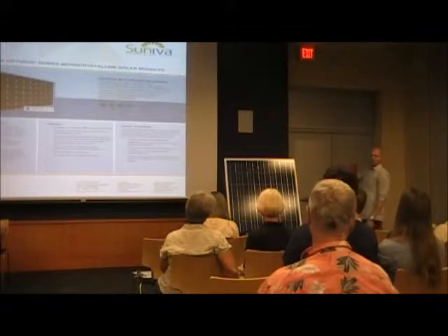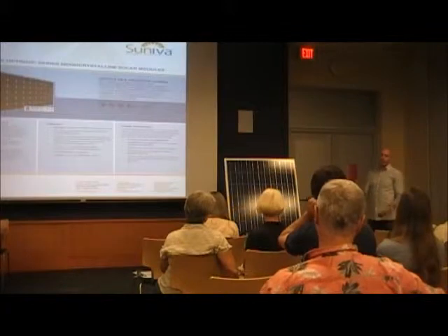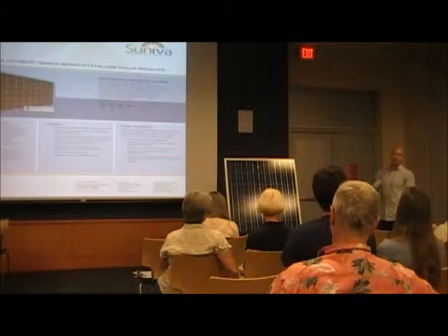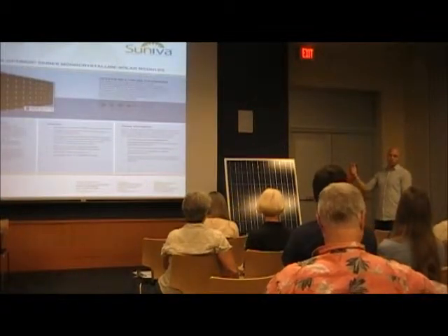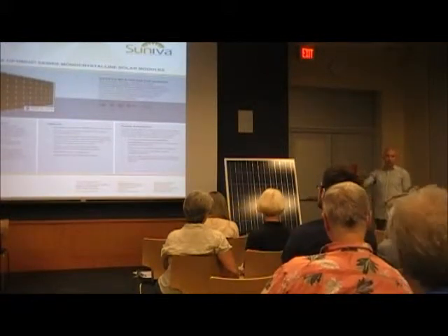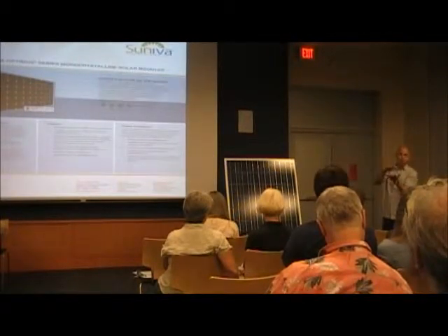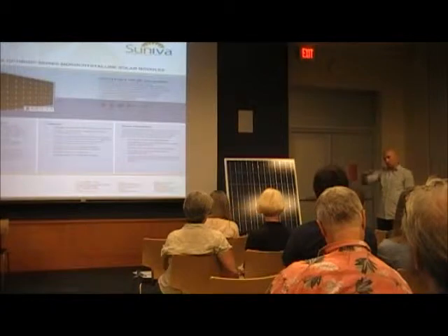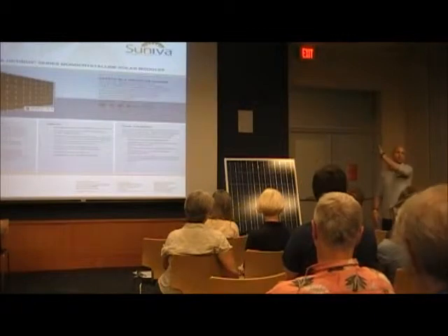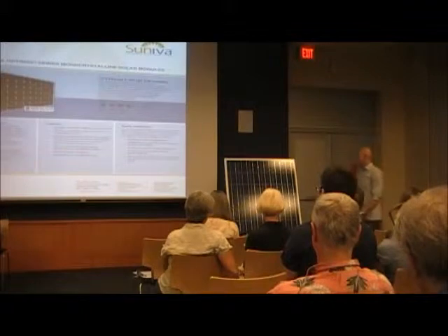The 25-year production warranties. So when you buy this stuff, the industry standard used to be that in the first 10 years it operated at 90% or better of the nameplate. And after that, from years 11 to 25, it operated at 80% or better. Now you're starting to see module manufacturers with linear degradation. On any module, once you install it, it's interesting: it's about a 3% drop, and then every year it drops about 0.5% of production. So if your energy costs are going up 5 or 10%, and your production level is only going down 0.5%, you're getting a huge benefit of that.